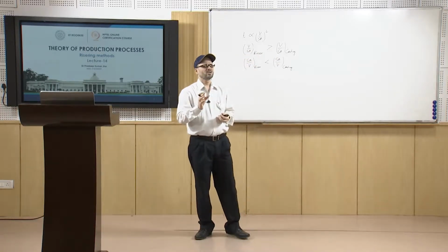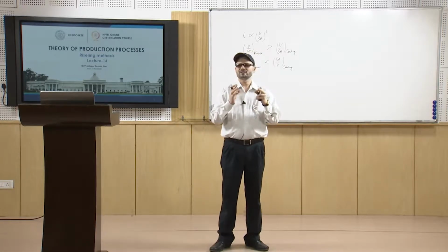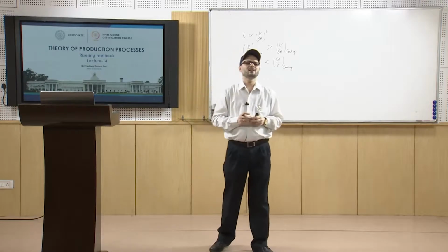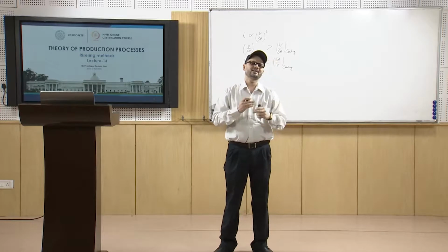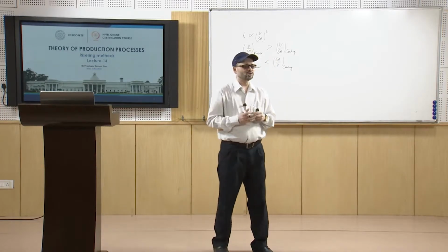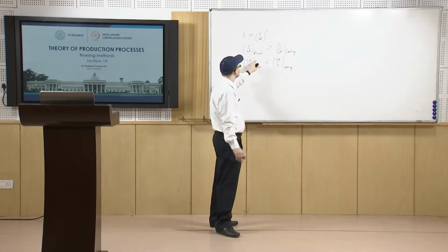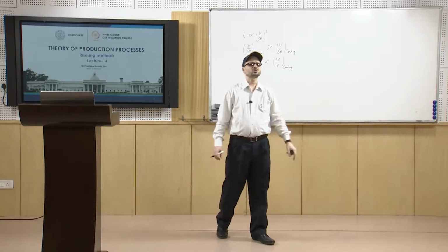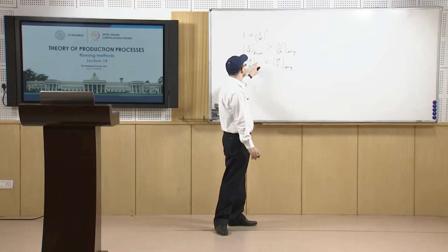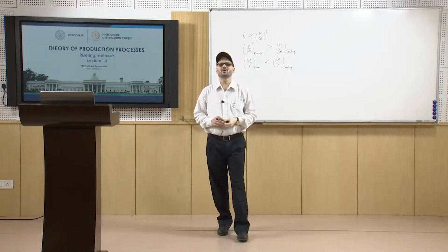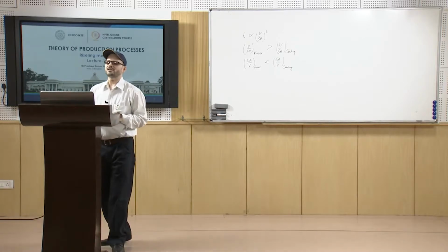So, both things are important. You must have sufficient volume of liquid metal in the riser, so that it can be fed whenever there is shrinkage in the casting. Also, this freezing characteristic condition should be satisfied: surface area by volume of the riser should be less than surface area by volume of the casting. These are the conditions which should be satisfied.